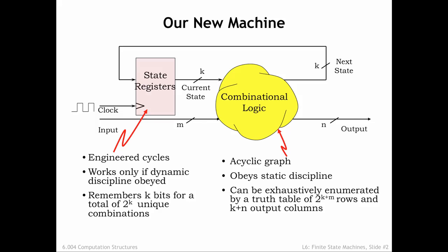As designers, we have several tasks. First, we must decide on what output sequences need to be generated in response to the expected input sequences. A particular input may, in fact, generate a long sequence of output values, or the output may remain unchanged while the input sequence is processed, step by step, where the FSM is remembering the relevant information by updating its internal state. Then we have to develop the functional specification for the logic so it calculates the correct output and next state values. Finally, we need to come up with an actual circuit diagram for the sequential logic system.